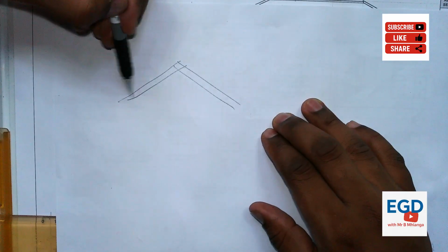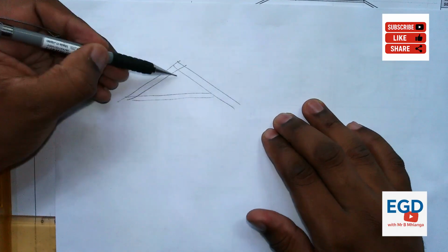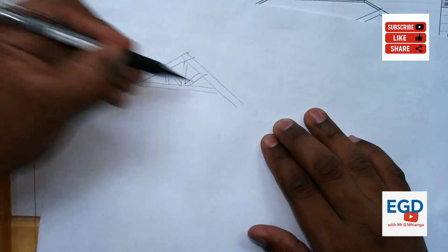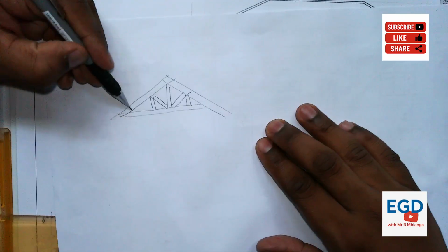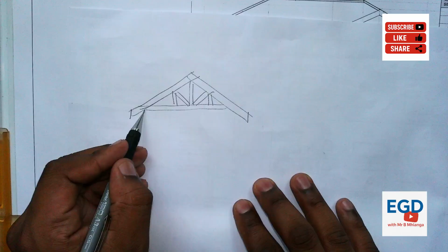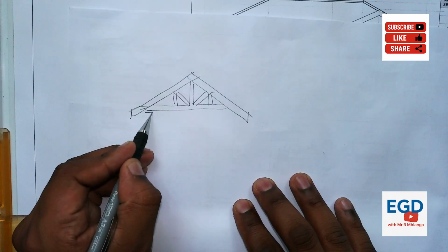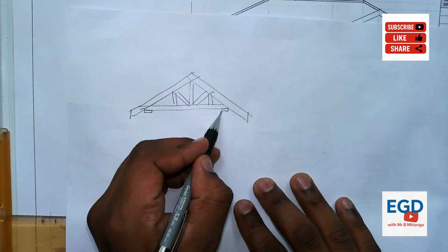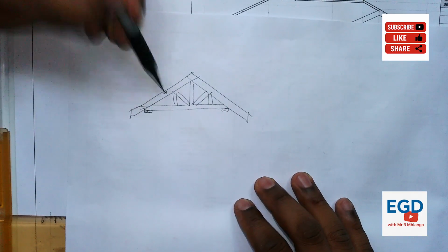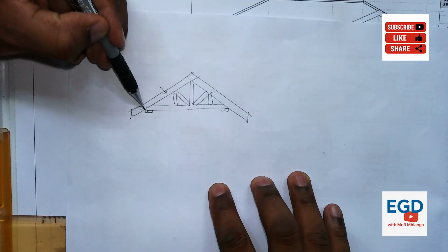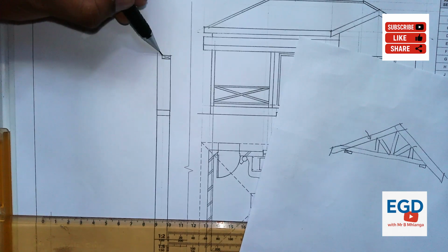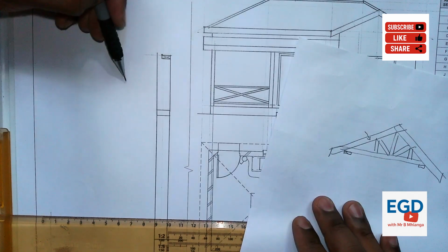We had something like this. This frame structure is called a roof truss. All right, so it was something like this. The wall plate is right there from both sides. All right, so obviously this component here, it's the rafter. So this rafter is resting on the wall plate at this point, right? That point is here for my drawing, right? So it means I'll have to draw a line across that point.